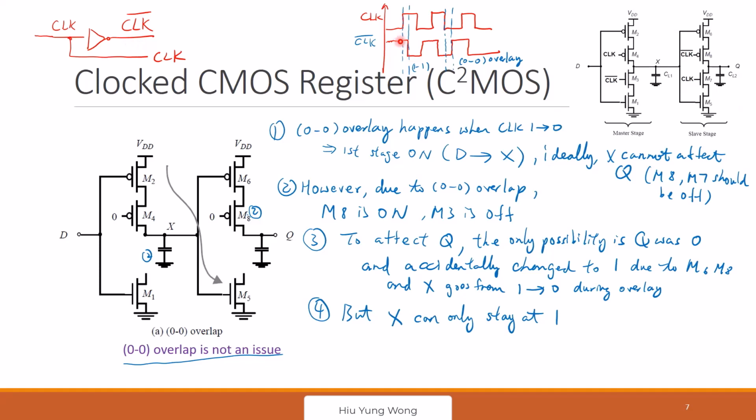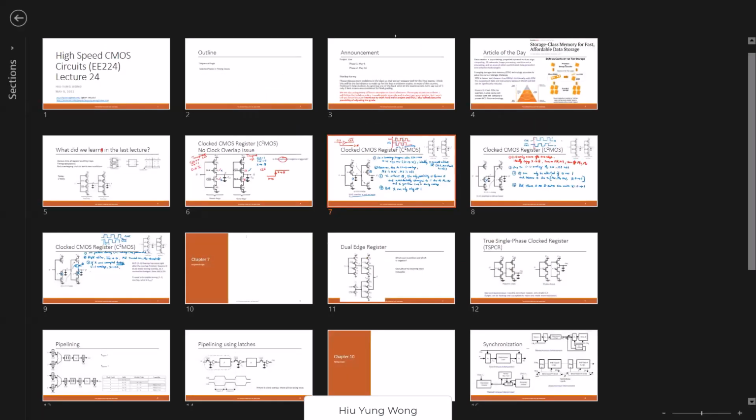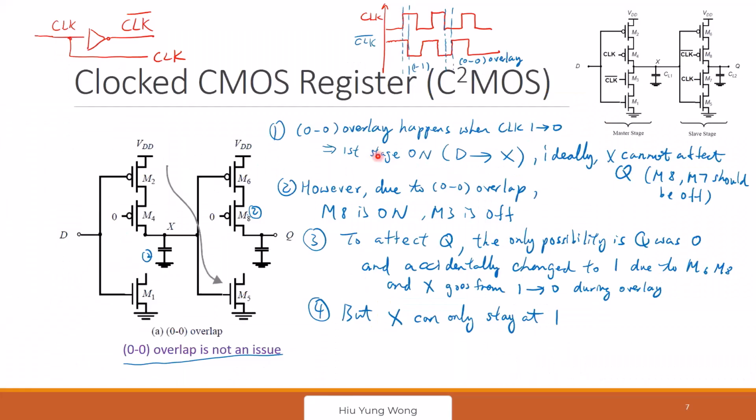It takes time to go from high to low. This is the delay, right? So this is like TPHL. 1-1 is like TPHL. 0-0 is like TPLH. Make sense? Yeah, that makes sense. So you see that all you learned before are all relevant, right? TPHL, TPLH.